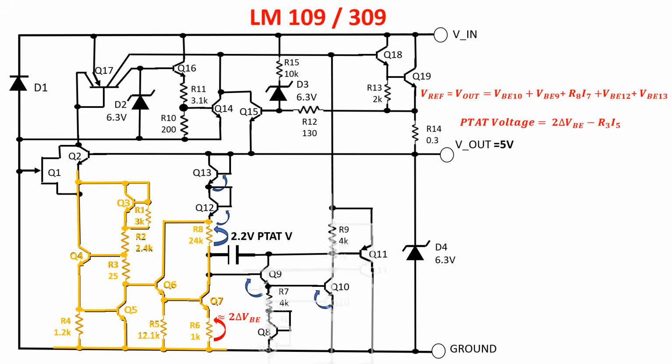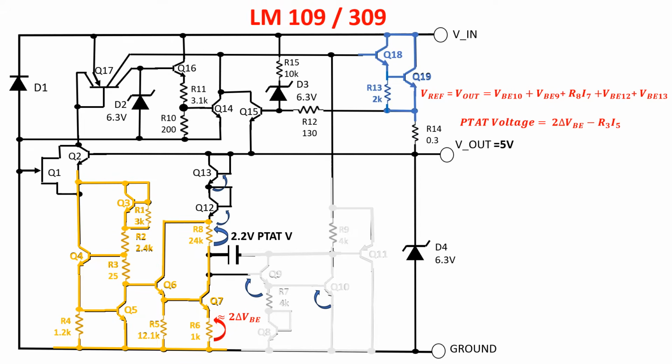Here the error amplifier for controlling the pass transistor and creating the negative feedback to stabilize the output. Here the Darlington NPN pass transistor. At the time there weren't good PNP Darlingtons, so NPN was a forced choice. Of course, the NPN creates a dropout which affects the power dissipation of the regulator.